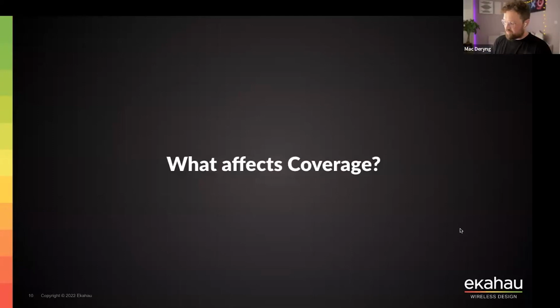Yeah, and on top of that, it's very important to repeat: if you have excessive contention, very high CCI, co-channel interference, anything that you do configuration-wise is not really going to help you. So we need to take a step back and do a redesign, okay? So CCI, you control it with a correct design, not with correct power necessarily. And about the design, it's not only about the number of access points, number of radios, it's also about the placement of these radios, correct mounting of the access points and antennas, and most importantly, choosing the correct type of antenna.